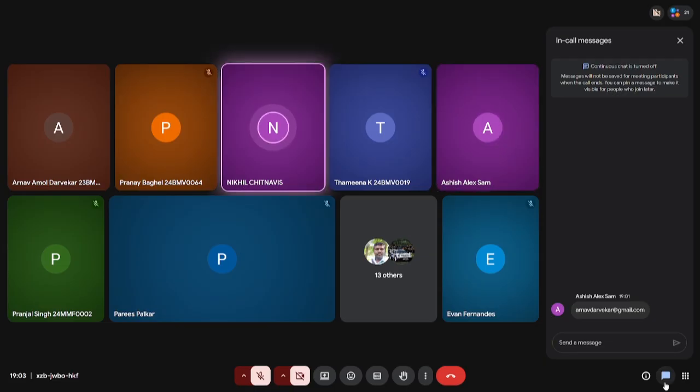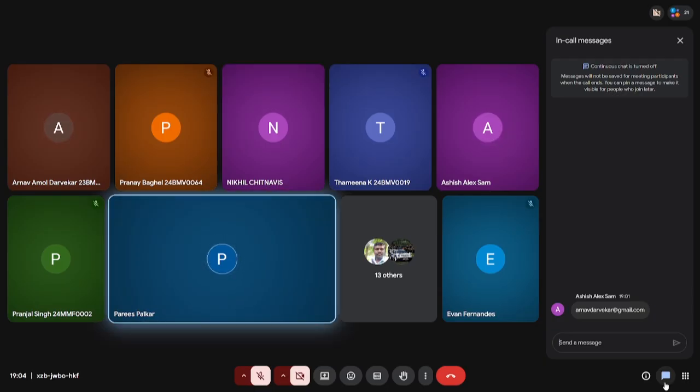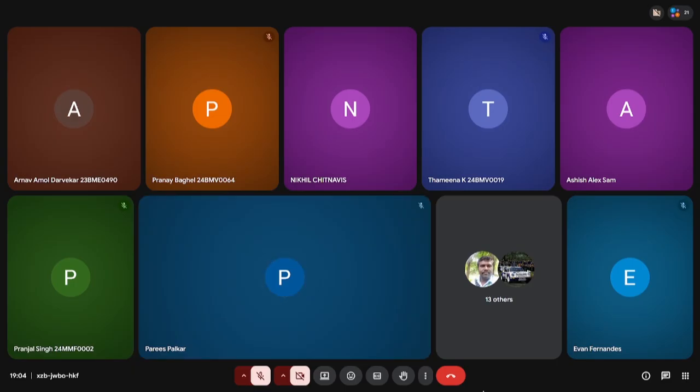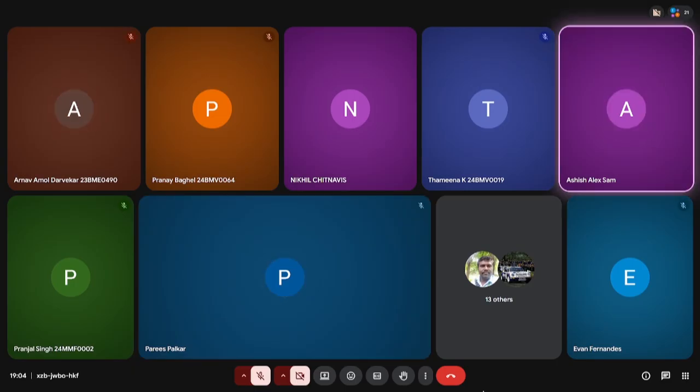No, in the snappyHexMeshDict file itself, you have to define the region where you want to give the local refinement, instead of going for other blocks. You can use a utility in snappyHexMesh itself. It is called box. So around your region, you can create a box refinement. You have to input minimum and maximum coordinates, and then around the domain of interest, a box will appear. So you can refine a particular region using that as well. Okay. Thank you, sir.